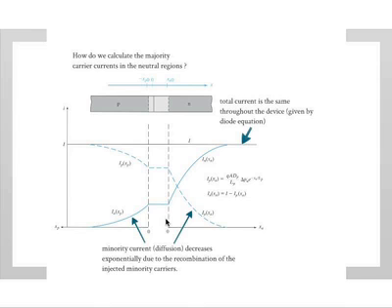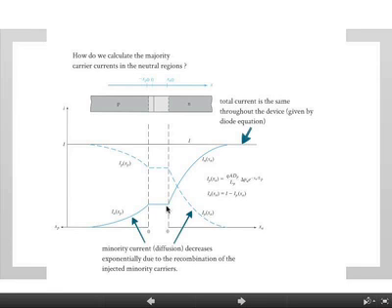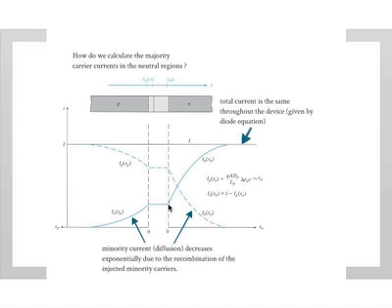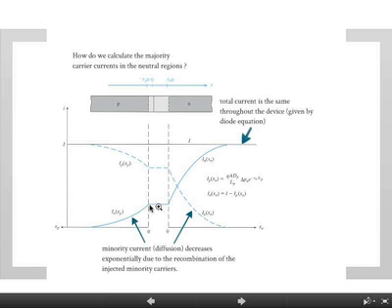So far so good. And we said that we just add the current here and the current here and you get the total current. We looked at two different positions and we add them up. But if you look at a single position, the total current is made up by the diffusion current of the minority carriers plus some current of the majority carriers. This excess current here is what gives you the total current here. So you have electrons here diffusing, and you have holes here also diffusing, but now in the opposite direction. Sorry, it's not drift, it's diffusion. We'll come to drift in a second.